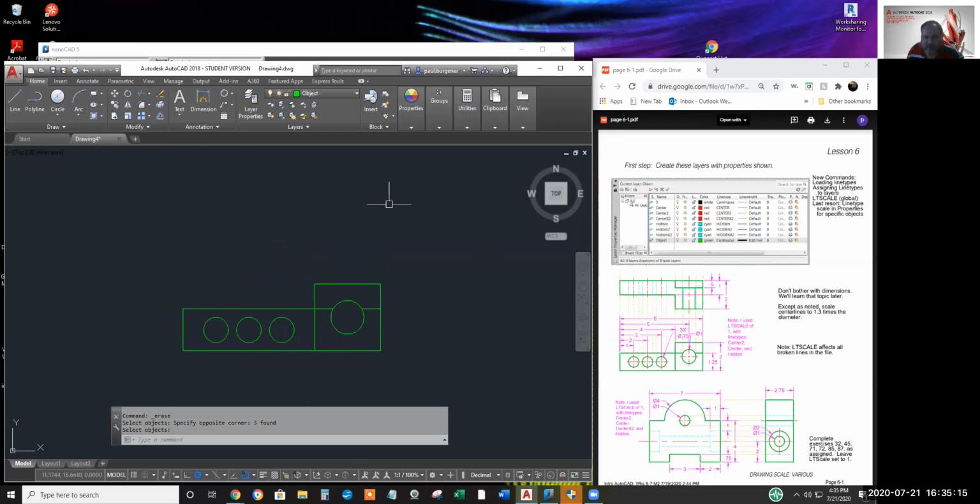Now the top view lines right to left should line up with the centers of the circles and the corners of the green lines. So being incredibly lazy, I'm going to draw a guideline, and it might be more impressive to put these on a layer named construction.